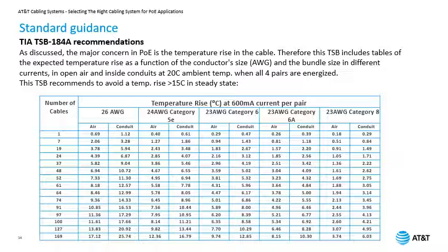This is the table shown here: the number of cables versus the temperature rise in centigrade at 600 milliampere current per pair.